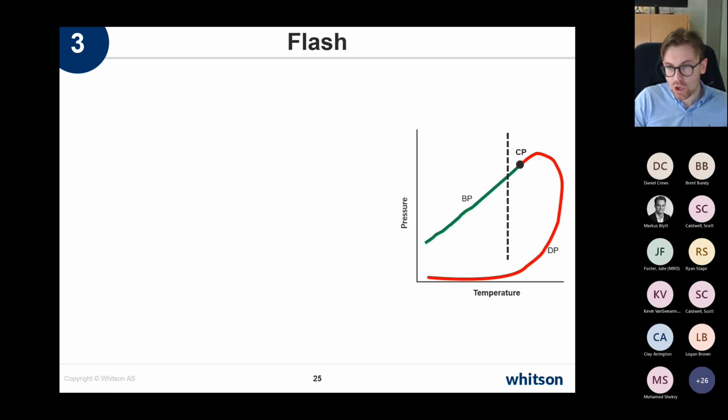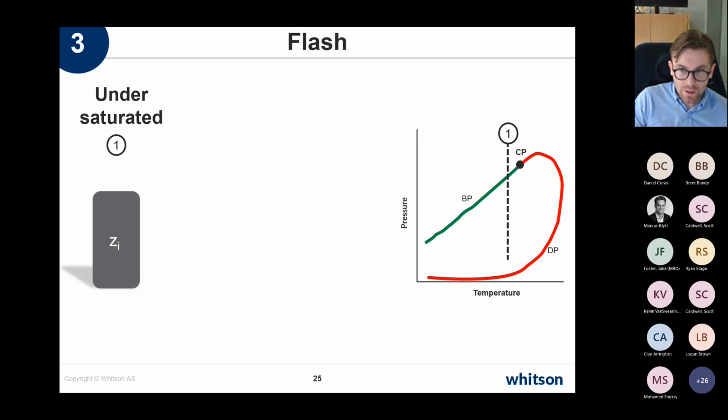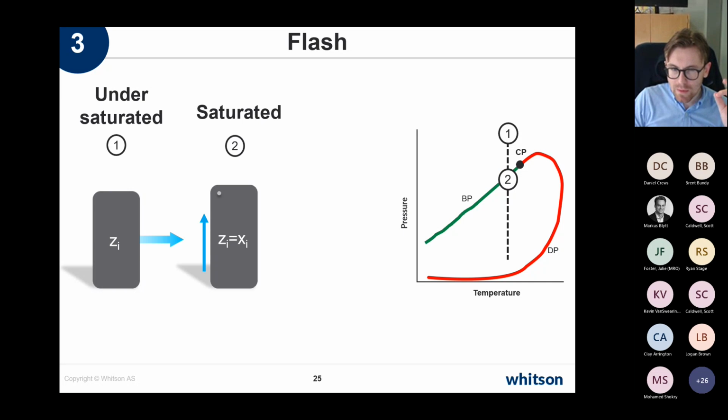Simple example here: you start with an undersaturated oil. Okay, this is an undersaturated, kind of near-critical oil at 0.1, that's the pressure. We have a phase envelope here to the right, which we'll talk more about. If I said that we would flash this composition at the saturation pressure, which is the bubble point for the oil, we would see a little, call it a bubble of gas coming out of solution. So you will have essentially primarily an oil phase, and then you'll have a super small, what's called an incipient phase composition, which is the so-called yi.